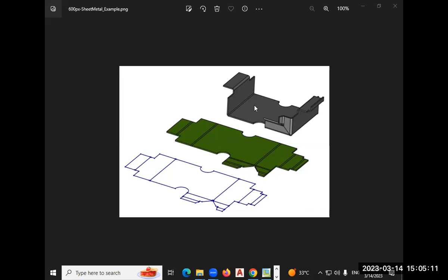So how to create this? Starting, you have to select the top view and select this base by using planar. By using extrude, you can create these two cuts. After that, you can add flange option and create this. Okay. Again, by using extrude option, you can remove these two materials. And like that, you can remove this and create all these parts and try to flatten this. Okay. So you have 20 minutes left. Try to complete this. Tomorrow we will see some more other options.